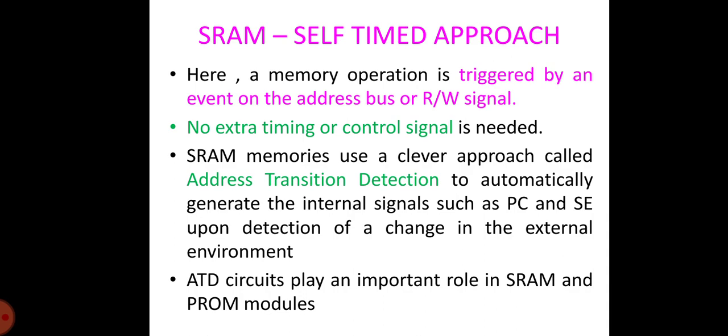Voltages at or below 1 volt are the norm for newly designed memories. The main reason for being limited is voltage stress, which can be endured by the very thin oxides used in cells. Consequently, the signal charge stored on the capacitor has dropped by a factor from the 64 kilobit to the 64 megabit generation.